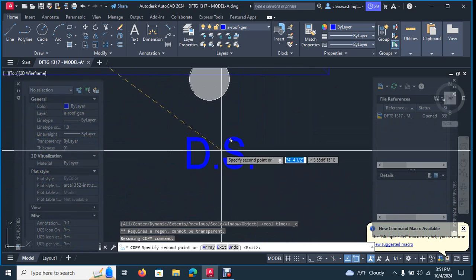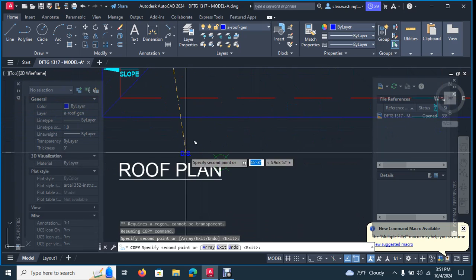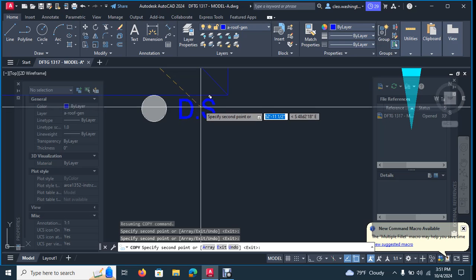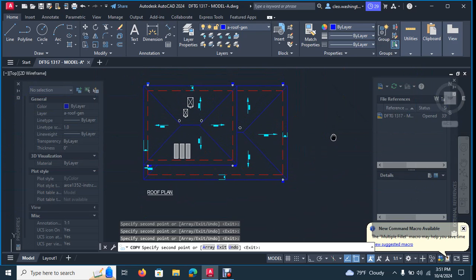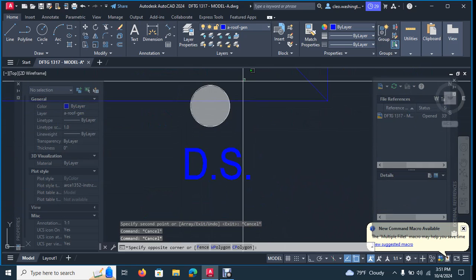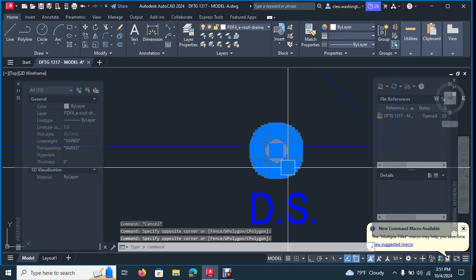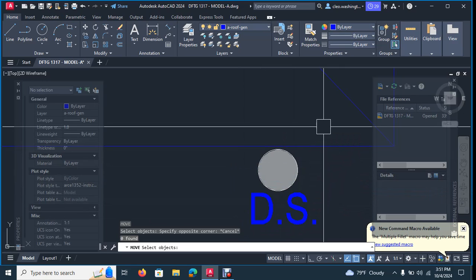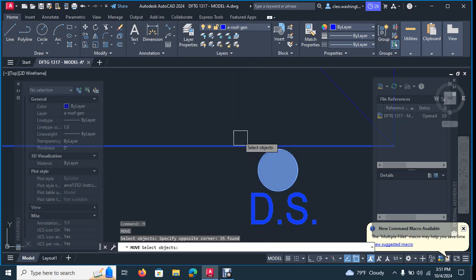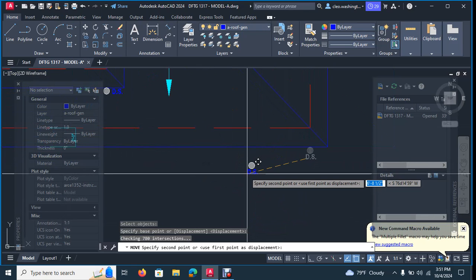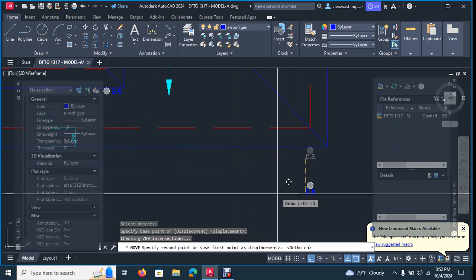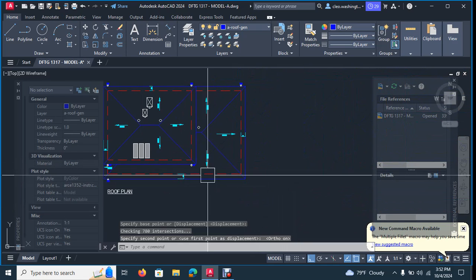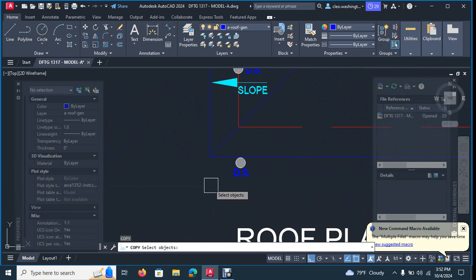Okay? And this one needs to move out some, so you can place it out a little bit. And then you can just put these here, these here. And then come here and select this, hold down shift and deselect that line, hit M for move and move it out some. And then hit M for move and copy this whole thing. Again, you're going to deselect that. And you're going to hit F8 just to keep it straight and clean. And we're going to drop it right here. Drop one right here. All right. Let me hit copy. So copy it back. I moved it.